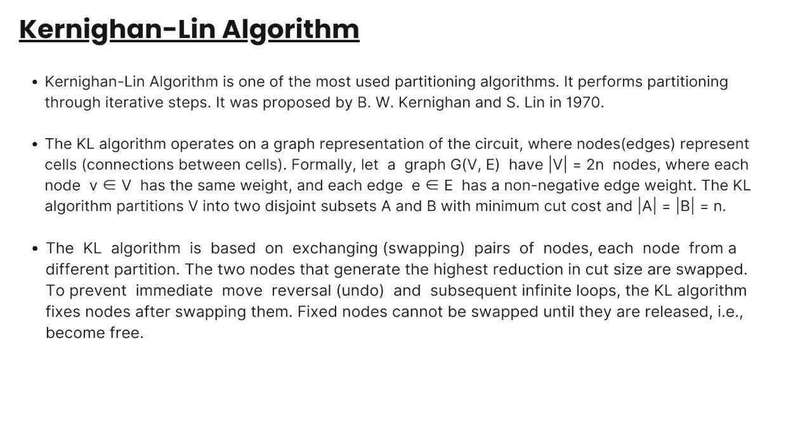Now we will learn the Kernighan-Lin partitioning algorithm. It is one of the most used partitioning algorithms, and it partitions the circuit using an iterative approach. The KL algorithm operates on a graph representation of the circuit. In this graph representation, circuit components are represented by nodes, and the connectivity of these circuit components is represented by edges.